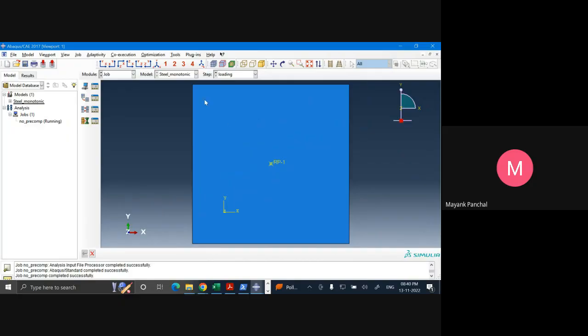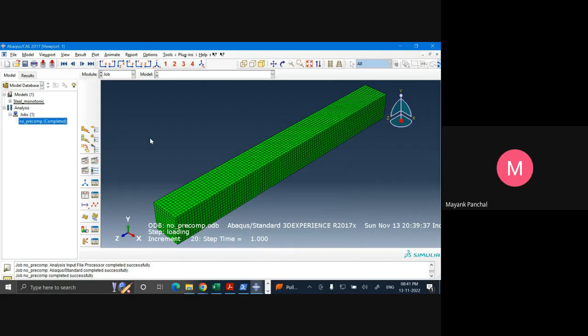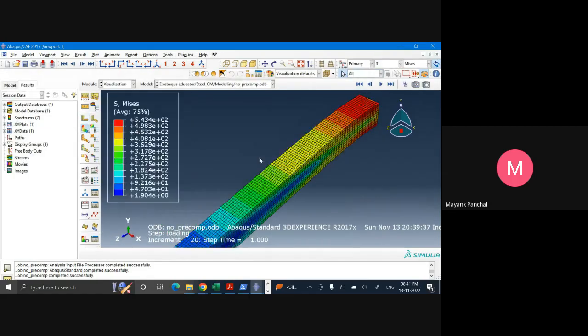And if the same material gives you close enough displacement or force capacity, then you should go with the section having the lowest material requirements. But you should also check for stability. That is the later part. Let's leave stability as of now.